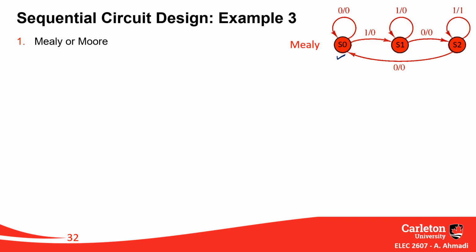So the basic strategy is, if you have a state which might give you different outputs, you split that state in two. So I have S2, and I make another state S2 prime, or S3. Opposite of minimization.